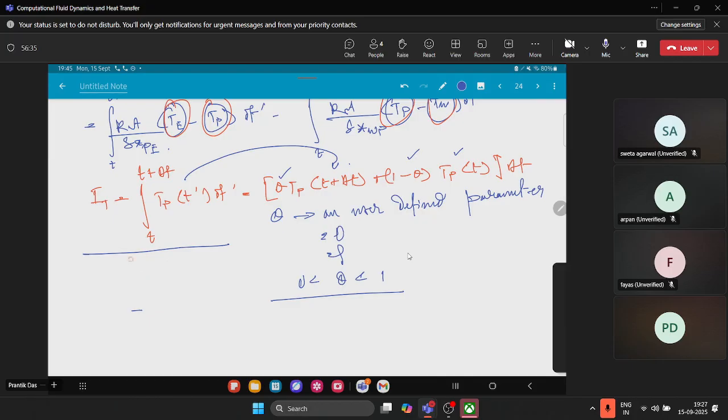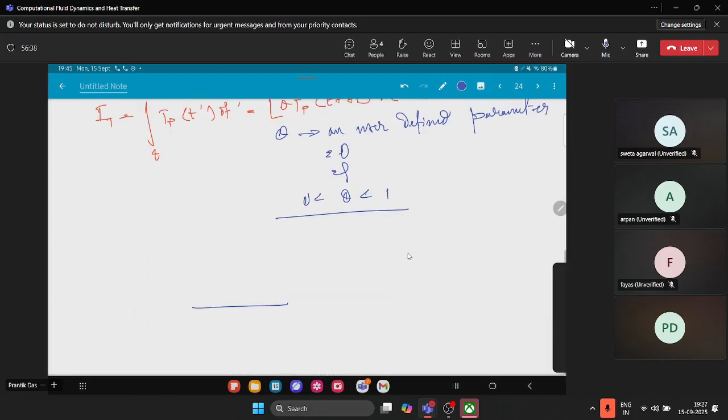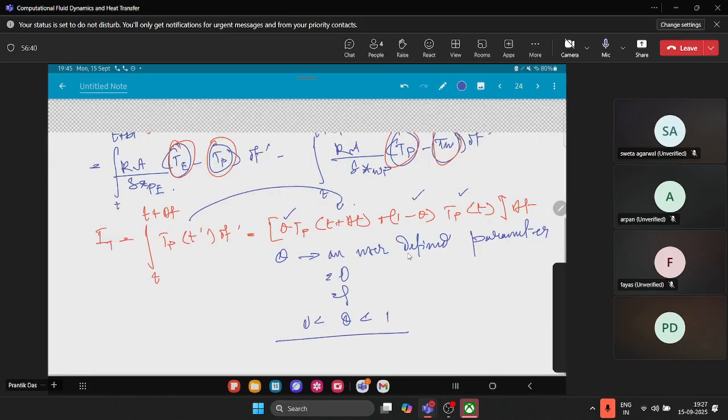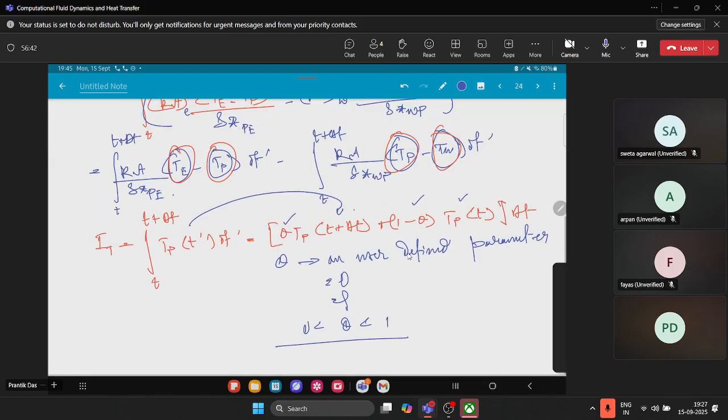These assumptions you will see when you are doing the simulation. After doing the simulation, if you don't see the results to be accurate, then you will kind of reverse engineer and see what the possible reasons for it are. Either the discretization scheme is wrong or the cell size is wrong. If you actually do multiple simulations over a period of time, you will understand what errors can come into play. Okay, that I will discuss with you at a later part.